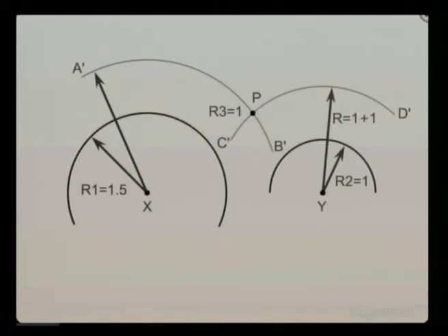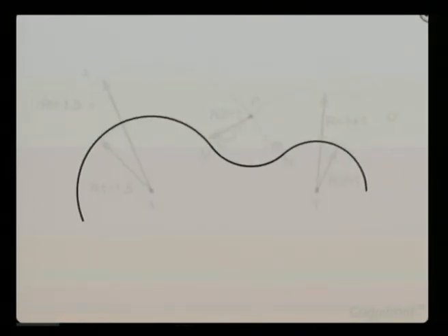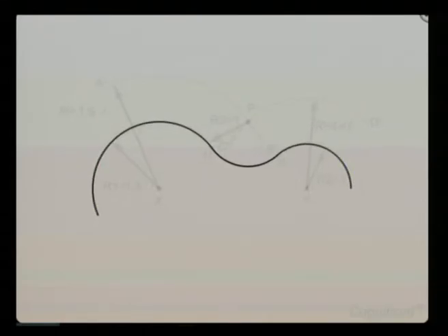With point P as center and radius r3, we will draw an arc which will be tangent to the given arcs at points M and N respectively. Let's now erase the unwanted curve segment. And here we go. We have just drawn a tangent arc to given arcs.